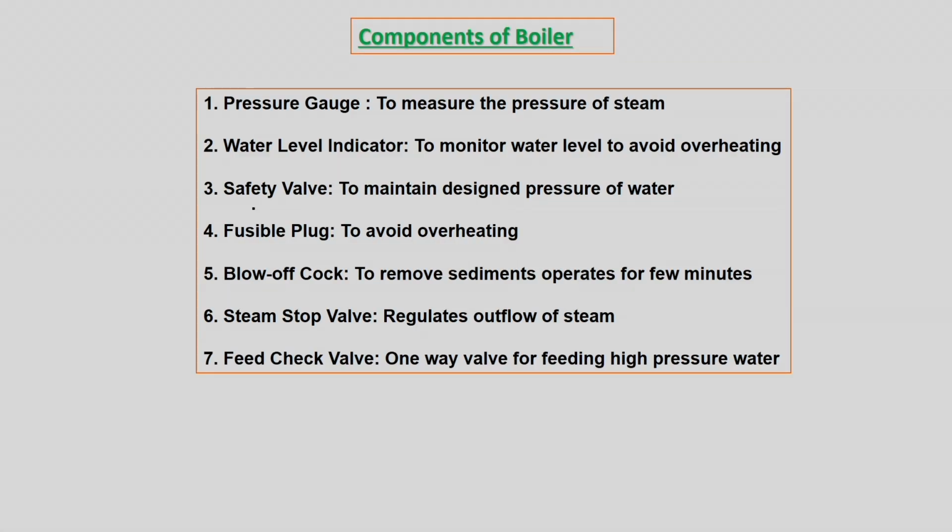It is important also for the loading aspect. Further, a safety valve to maintain the designed pressure of the water. We should have a fusible plug to avoid overheating. We should have a blow off cock to remove the sediments which are present during the operation, and then we have the steam stop valve which regulates the outflow of the steam. We have the feed check valve which is a one way valve for feeding the high pressure water into the steam generator. So, these are some components of the boiler.